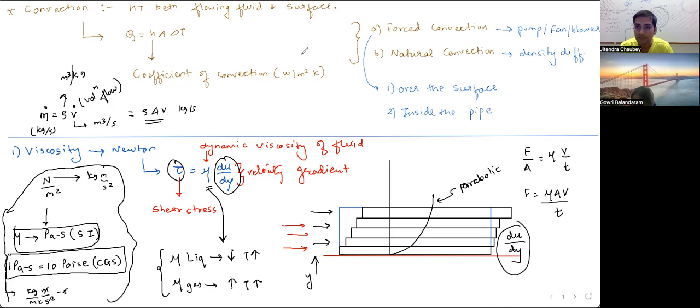One last one. Natural convection, the steps will be: first, you need to calculate Grashof's number, and for that, all the terms in Grashof's number, like g, beta, delta T upon nu square, so you must know beta, delta T and nu before that. Grashof's number is the first, then Prandtl number, then Nusselt number, and then h.